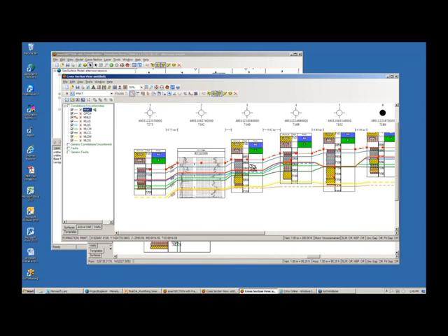All you do is hit the Tab key on your keyboard, and the Picker tool becomes the Select tool, and you can just move your surface up and down at will. Then if you want to continue picking, you hit the Tab key again, and you're on your way. So no need to keep coming up and down from the toolbar. We've tried to really make the flow of picking very easy. All right, so that's the bottom line. It's that easy to go ahead and pick.